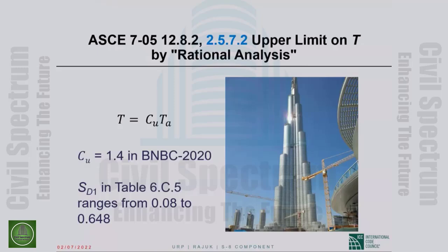That is not the point, that's not the purpose of rational period computation. That actually defeats the purpose. It is not supposed to be a license to lower your design base shear just as much as you would like. So that being the case, there are limitations, there are restrictions on rationally computed period.